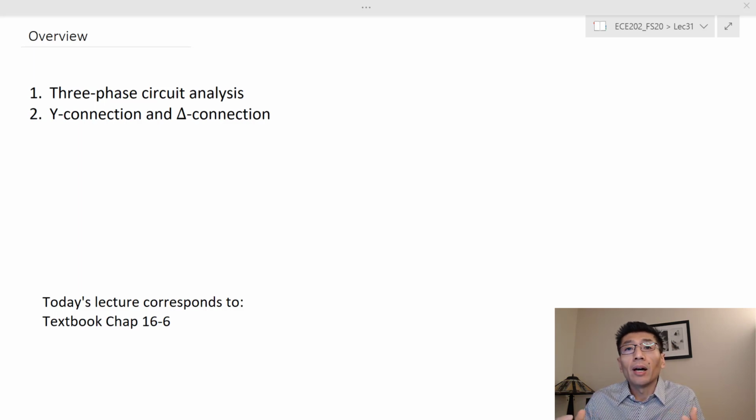if the three-phase circuit does not have the neutral line already, we could add the neutral line, so we can single out one phase out of the circuit. We call this the per-phase equivalent circuit, and we can solve that very similarly to single-phase circuit analysis, except that if you ask about the three-phase power, make sure you multiply by 3, because in each phase the load impedance is the same, and they will absorb the same amount of complex power, right?